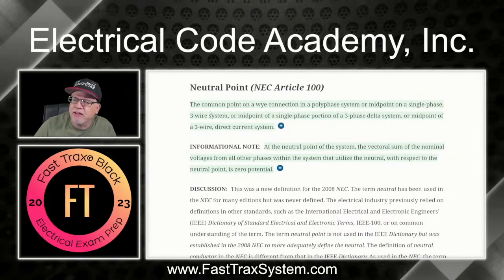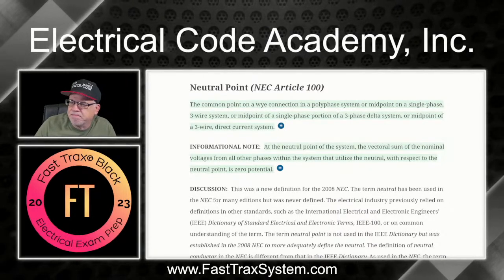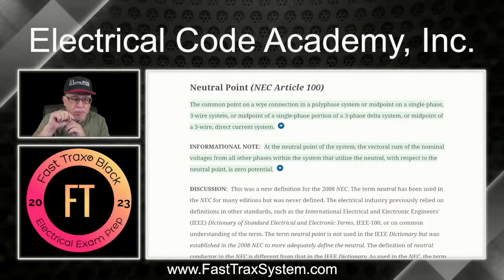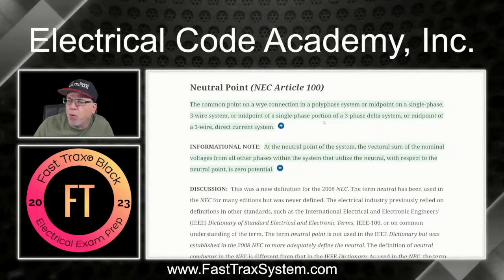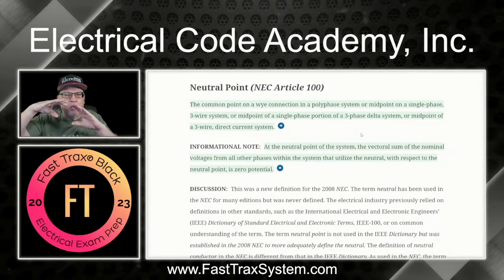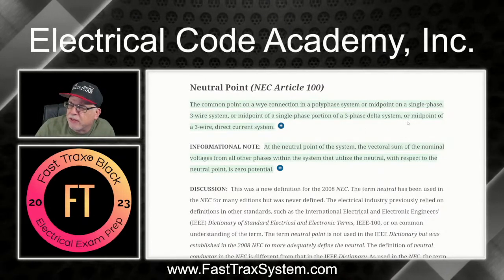So here's what it says. It says a common point on a Y connection in a polyphase system, and that's that midpoint. We'll look at a graphic here in a second. Or the midpoint on a single phase 3-wire system. So again, that 120, 240 volt winding, that midpoint connection, okay, that creates a neutral. Or the midpoint on a single phase portion of a 3-phase delta. So you have A, B, and C delta, and you're just taking one winding, and it's the midpoint of one winding, okay, creating a neutral point. And of course, it also talks about the midpoint of a 3-wire direct current DC system.